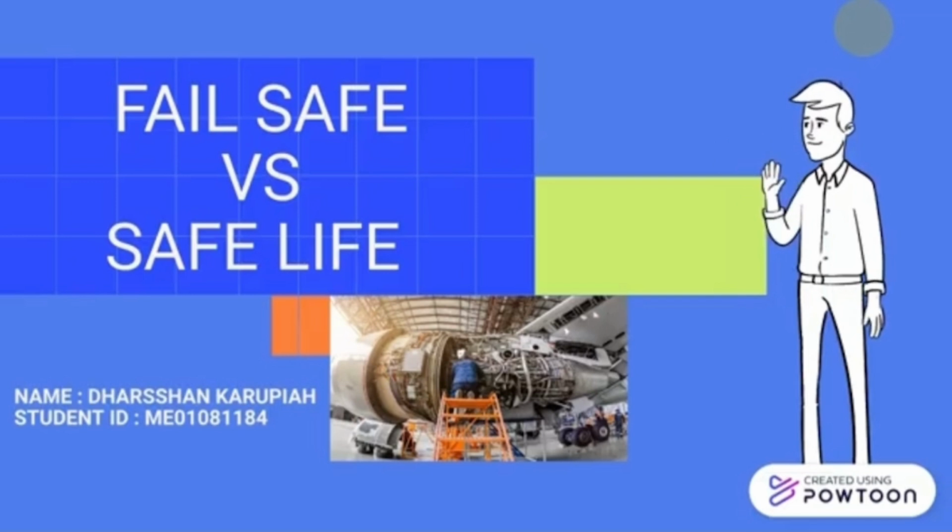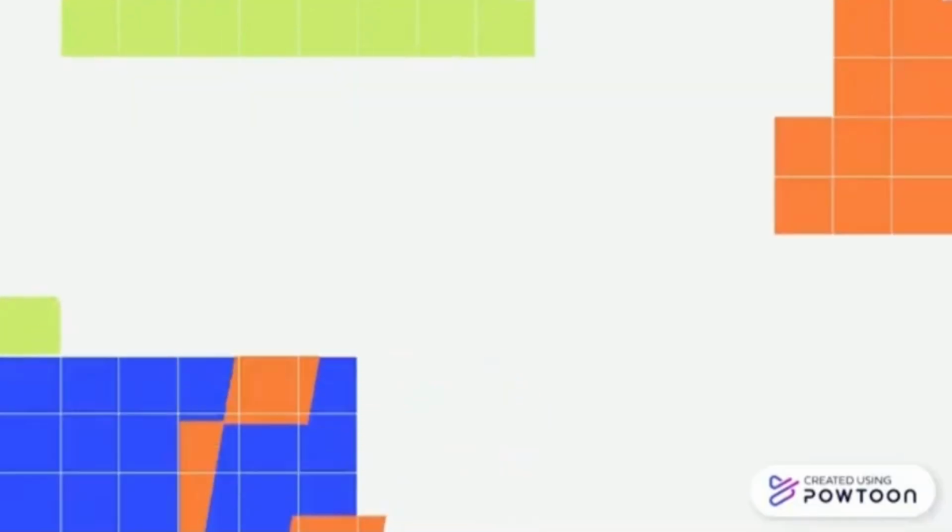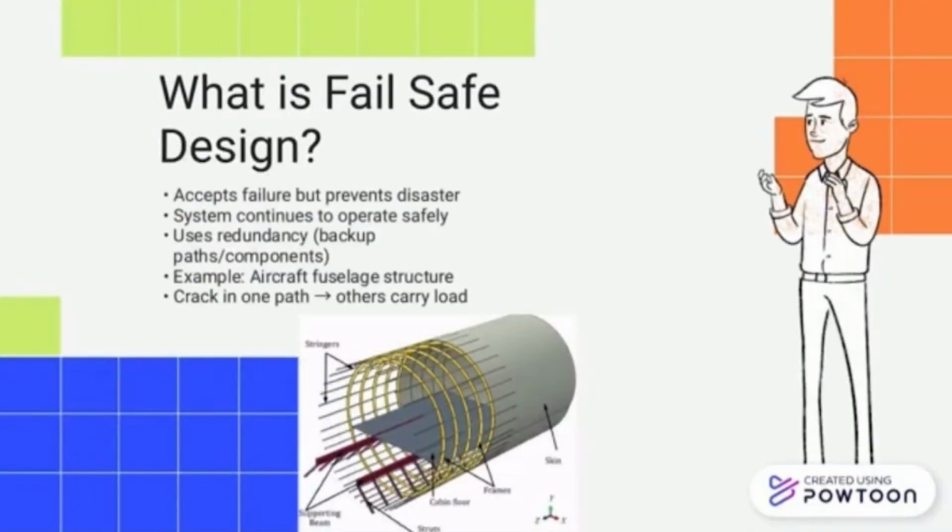Today we'll explore a vital topic in mechanical engineering, the difference between fail-safe and safe life design. To make this easy to understand, I will explain it using an example most of us are familiar with, an aircraft system. Let's begin with fail-safe design. In simple terms, this design method allows for the possibility of failure, but ensures that the system remains operational and safe even after the failure occurs. It's about making sure that the failure doesn't result in disaster.